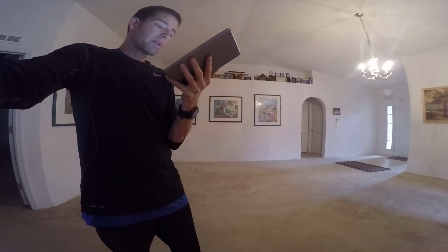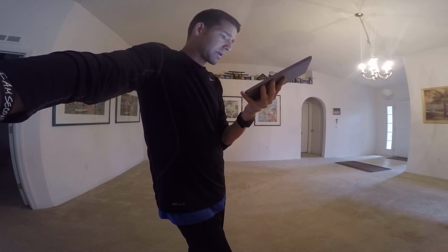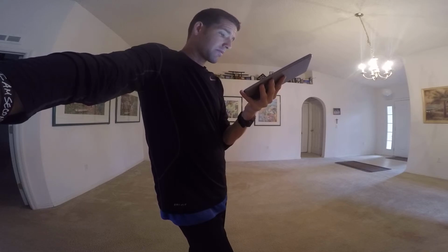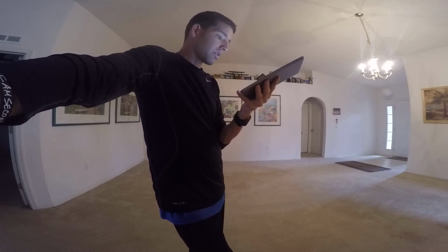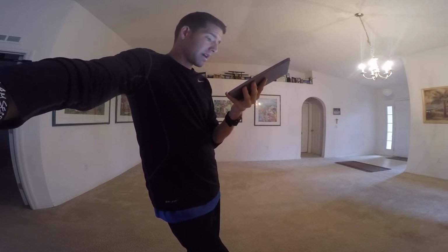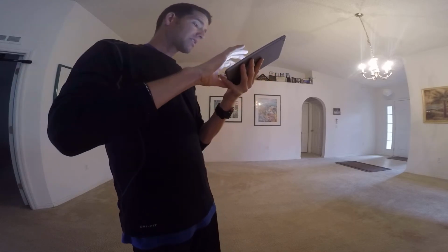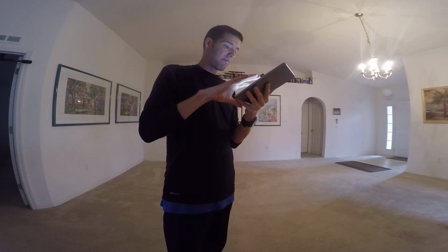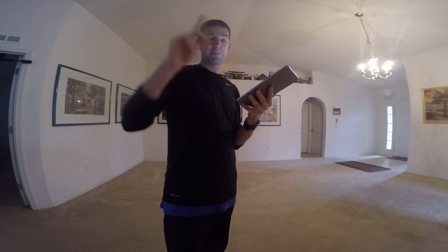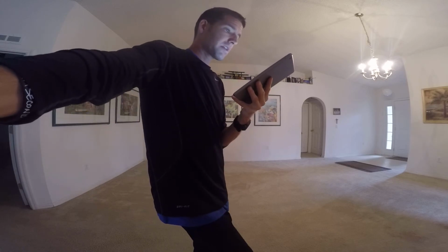The combination of blade flapping and slow relative wind acting on the retreating blade normally limits the maximum forward speed of a helicopter. At a high forward speed, the retreating blade stalls because of the high angle of attack and slow relative wind speed. This situation is called retreating blade stall and is evidenced by a nose pitch up, vibration, and rolling tendency, usually to the left in a helicopter with counterclockwise blade rotation. Pilots can avoid retreating blade stall by not exceeding the never exceed speed. This speed is designated V, big V with an NE, and is indicated on a placard and marked on the airspeed indicator by a red line.